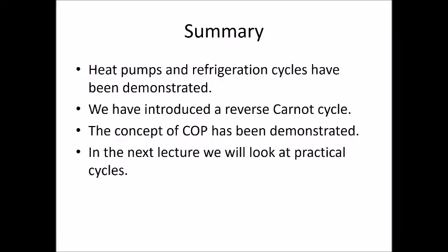So what we're going to look at now is more practical ideas, and obviously we're going to take our Carnot cycle, our reverse Carnot cycle, and we're going to look at what we need to do in order to make it much more practical, in the same way that the Rankine cycle is more practical than the Carnot cycle. So have a think, two-phase flow, that kind of thing. Do we really want to deal with 2 phases in our refrigerator pump, or are we going to do some subcooling and superheating just as we would do in a power station forward Carnot cycle?